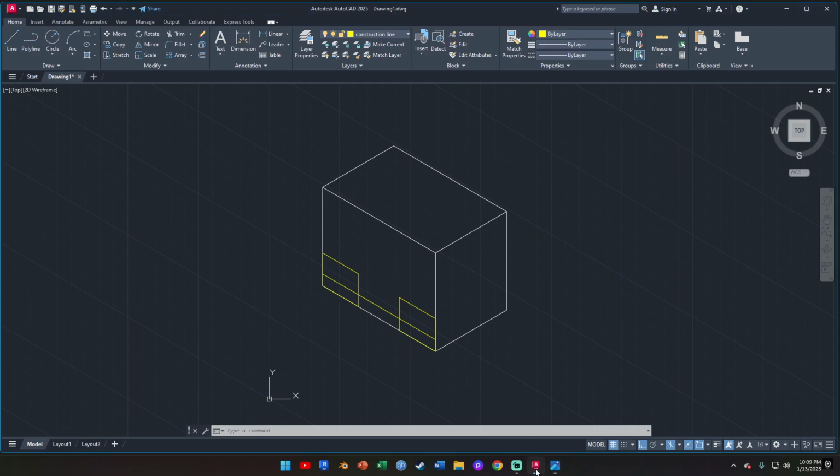So we can go back to the construction here, and since we know that this line has to go in 25 mm, we can basically copy it, and here I want to notice an issue. The line isn't moving how it's supposed to be moving. The reason for this is because we're on the wrong isoplane.